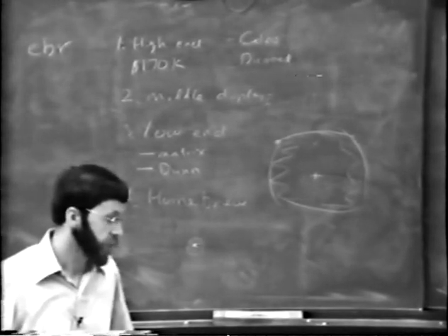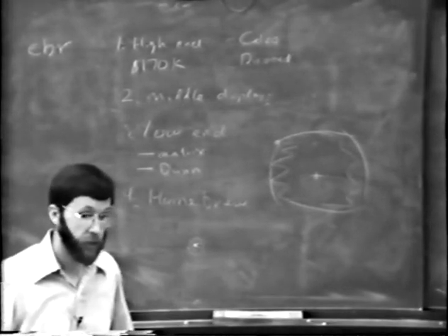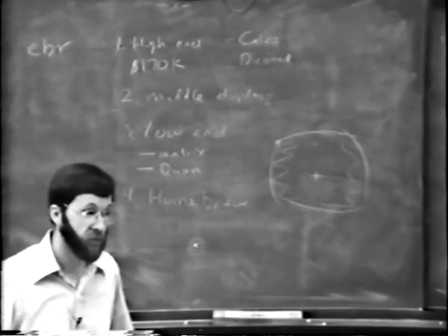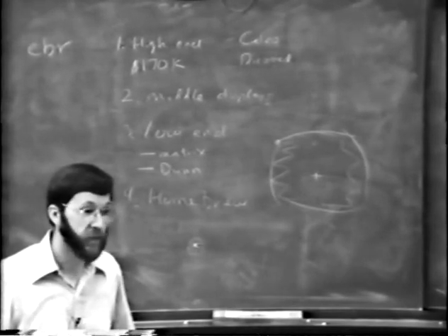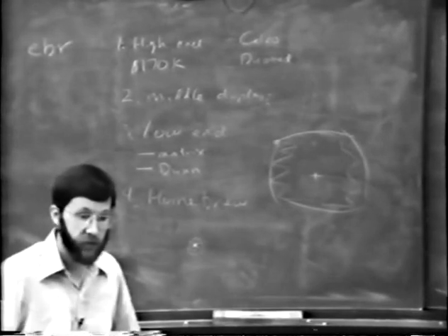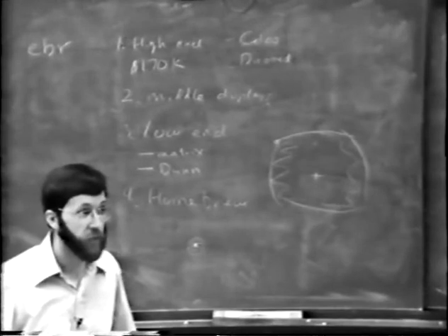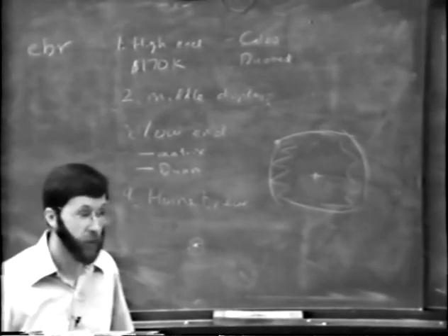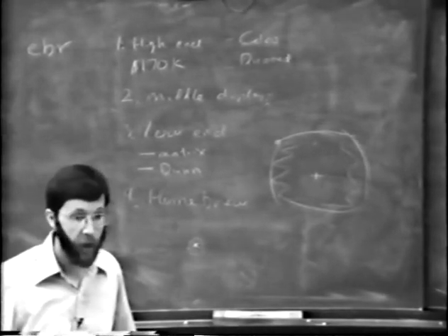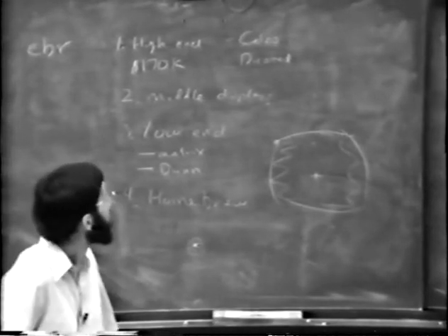The size of the beam, or the dot on the face of the CRT, is roughly comparable to a grain of phosphor. And the phosphors themselves have a 15% variance in their size, which introduces this noise on top of things. And for some of their work, although you can't do it for film writing, you can for film input, they can actually compensate for that noise. In any case, we have considered that.